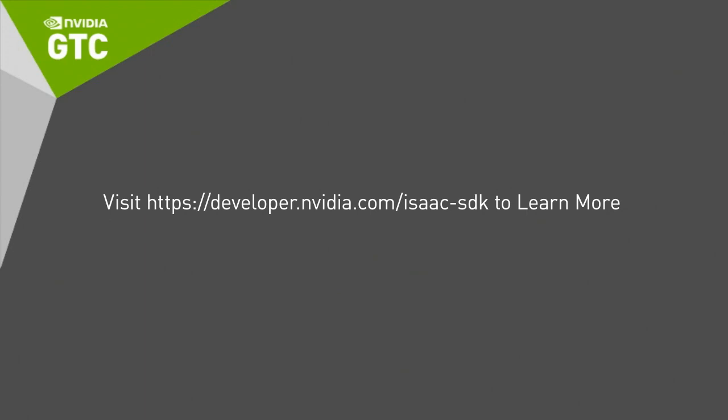One is I didn't provide too much explanation for what URDF stood for. That stands for the Universal Robotics Description Format. URDF files are generally provided sometimes by the manufacturers or by researchers. So, for example, for the Franka Panda arm, there's a GitHub repository that provides you the URDF that you could load into ROS, into RViz, and that same URDF is what we load into the simulator.